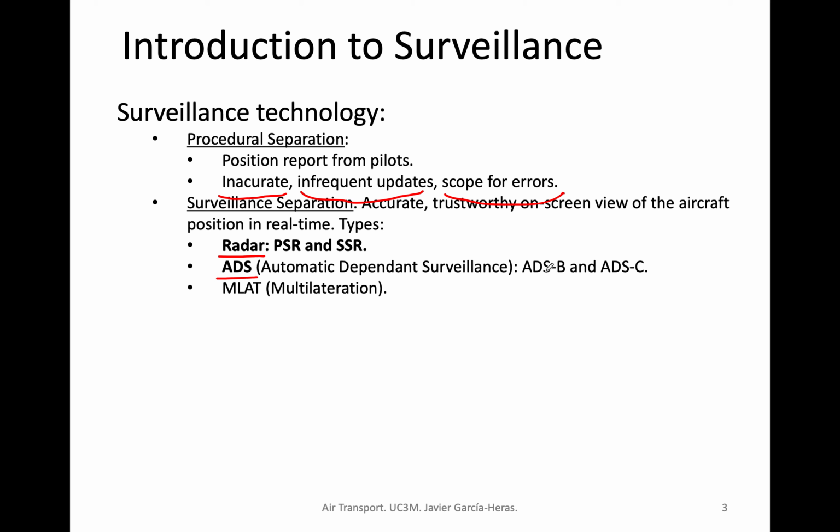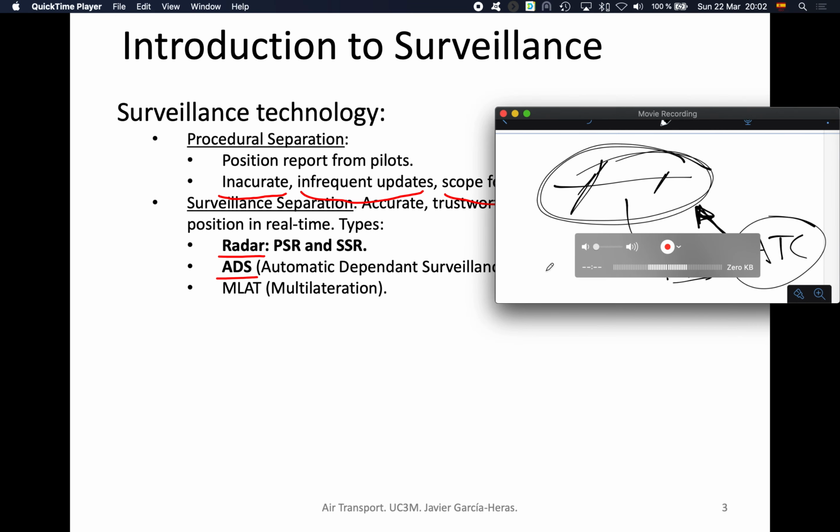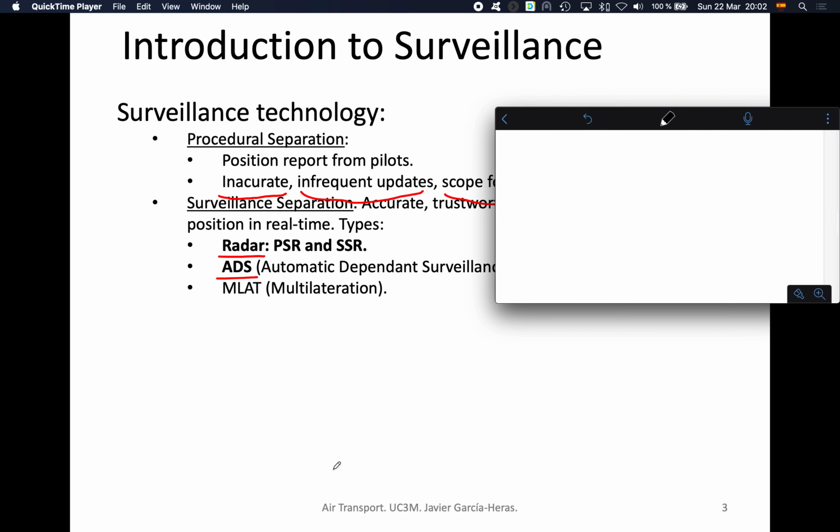It uses a technique known as time difference of arrival to establish surfaces which represent constant differences in distance between the target and the pair of receiving stations, and determines the position of the aircraft by the intersection of these surfaces. This is pretty much what I mentioned here.